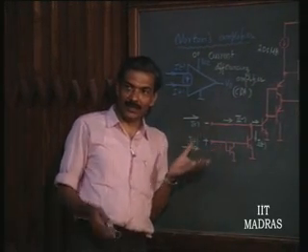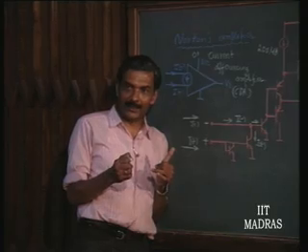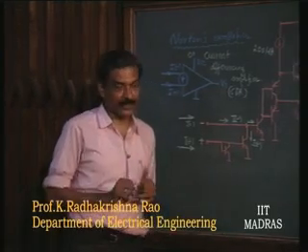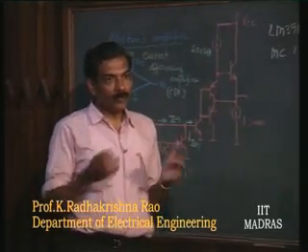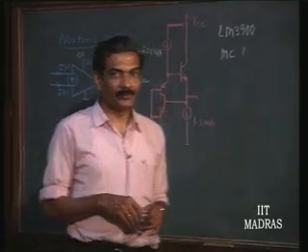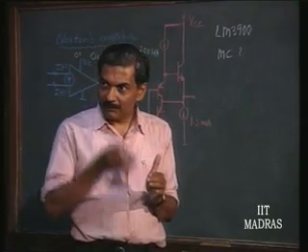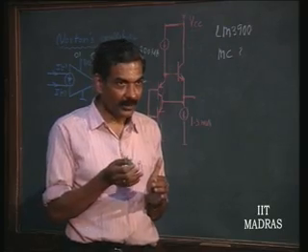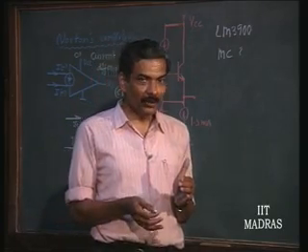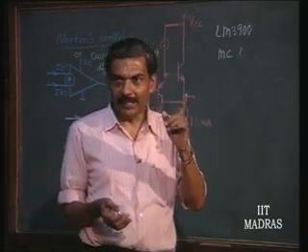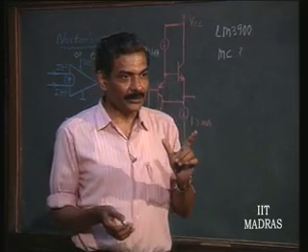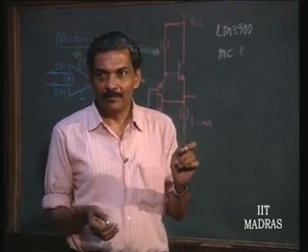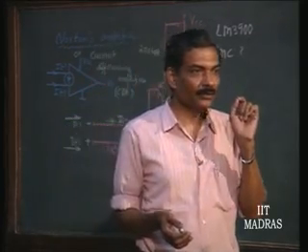and it has become quite popular. Only thing is you have to look at it slightly differently compared to what you were doing earlier. What is this difference? How are we looking at an op amp? Op amp was being used in a negative feedback situation. When it is used in a negative feedback situation, if the op amp open loop gain is very high, then we said the input voltage V1 minus V2 becomes equal to 0.